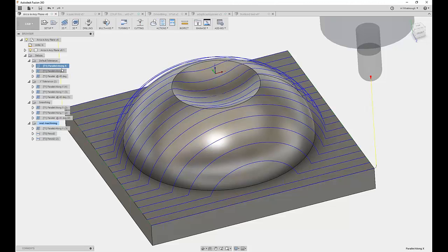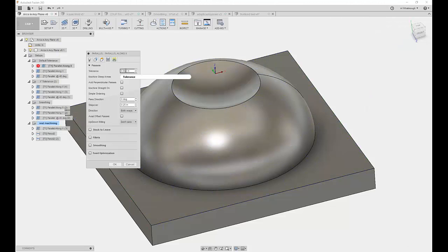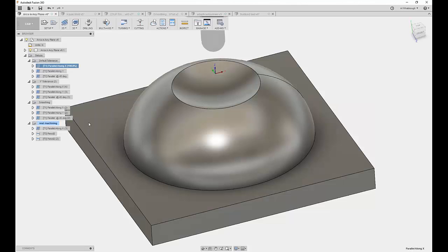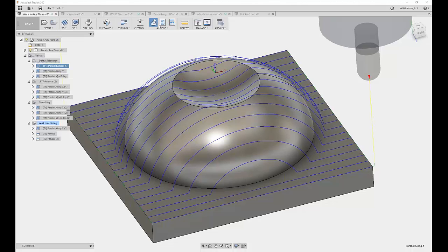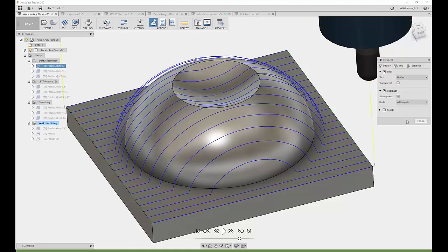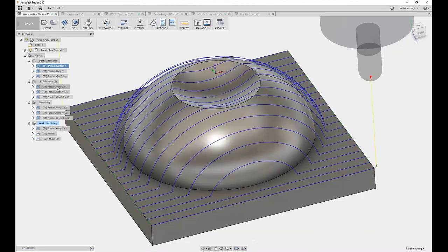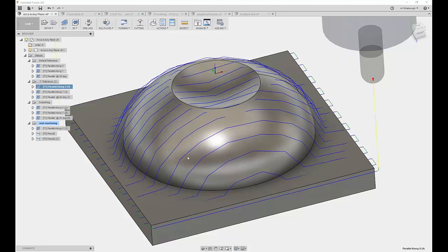How many little lines am I going to get to simplify things? Then we can say I want to apply smoothing, and that's going to go fit an arc through a series of those lines. So when I apply the smoothing to it, it does mean the toolpath calculation is a hair longer, but now you fit the arcs through it, and now I've got a series of large arcs that went through all the toolpath. And just to visualize, here's an example of a toolpath that has a very jagged set of lines.